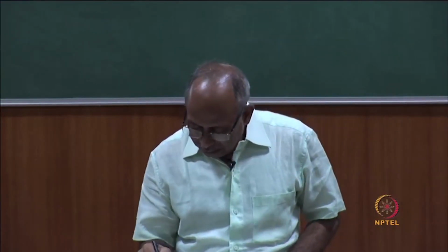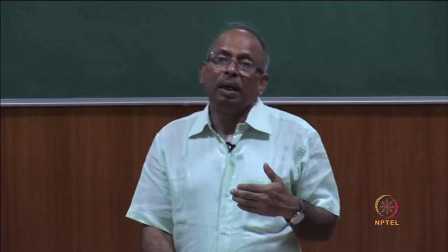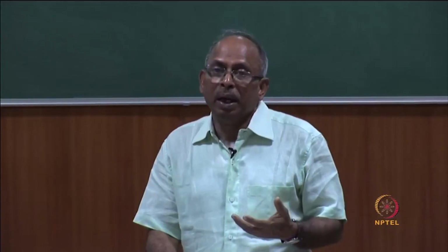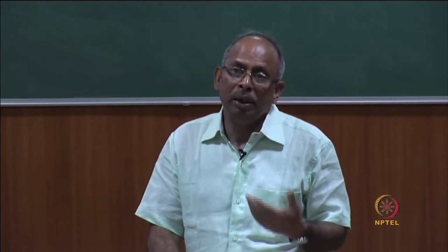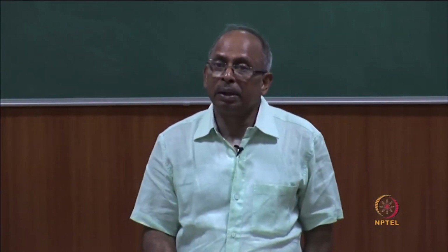Creep would have caused some sort of deformation, but then this is restrained, no movement can occur, so this horizontal movement is prevented. So, additional force will come in. This will neutralize the effect of applied stress, I mean this is just an example, and relaxation will reduce stress concentration. Also, shrinkage stresses get reduced.